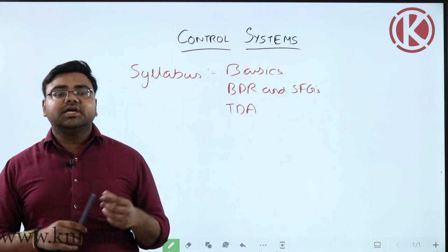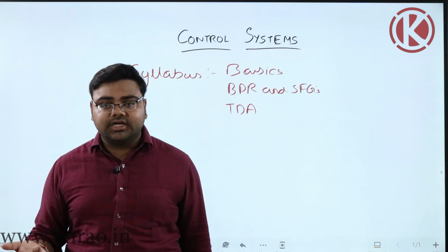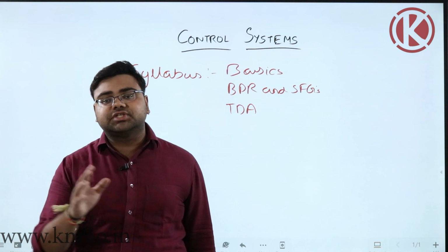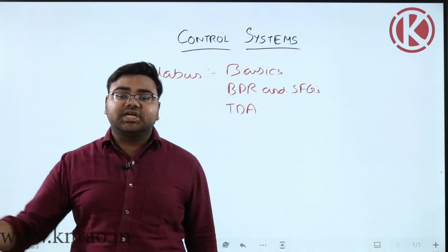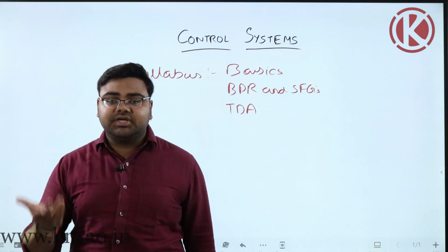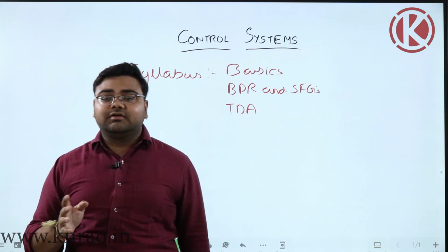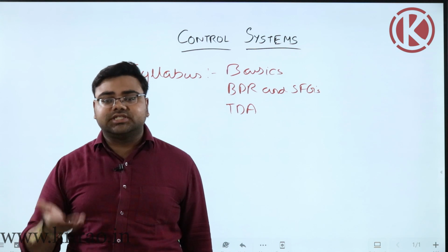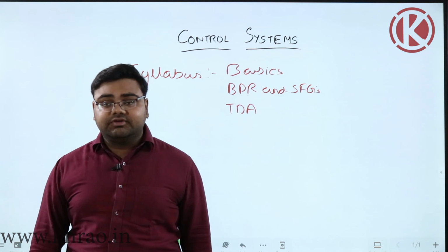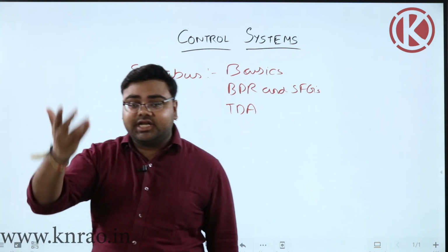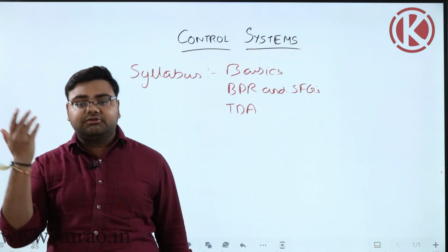The reason for that is, if you have first and second order, putting them in cascade can give you all higher order systems. So if you have a third order, just split it into a first order and a second order, analyze both separately, and because they are LTI systems, you can simply merge the outputs and understand the behavior of the higher order system. But the problem is that always doing this, say it is 4th or 5th, okay fine, still you will be able to manage it. But if you have a 10th order or a 12th order system which is actually practical, like for example, an unmanned aerial vehicle which is a 12th order system, suppose you were to linearize that, you will have an s power 12 term in it.